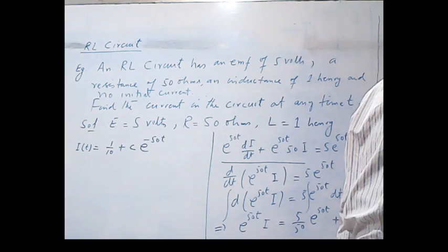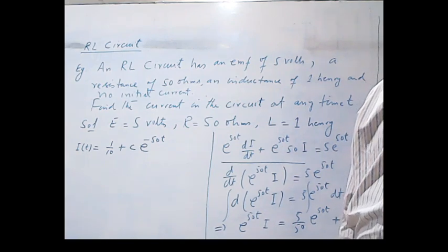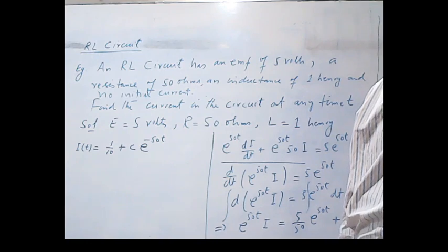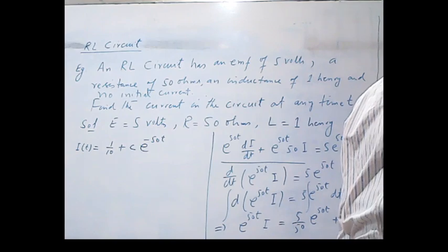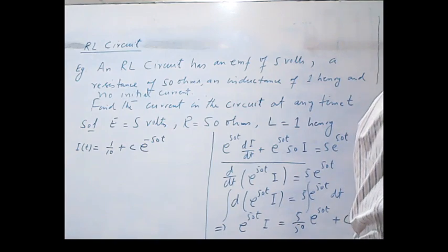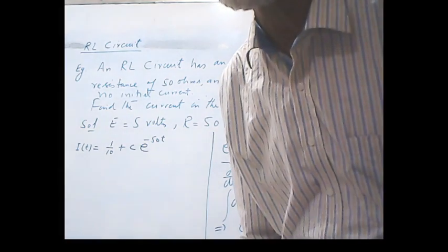So sometimes the data involves finding the charge, but we have the model in terms of I. So use the model in terms of I. After solving for I, change I into dq by dt, again integrate, again the model is in the form of first order linear separable variable form, and then simplify.